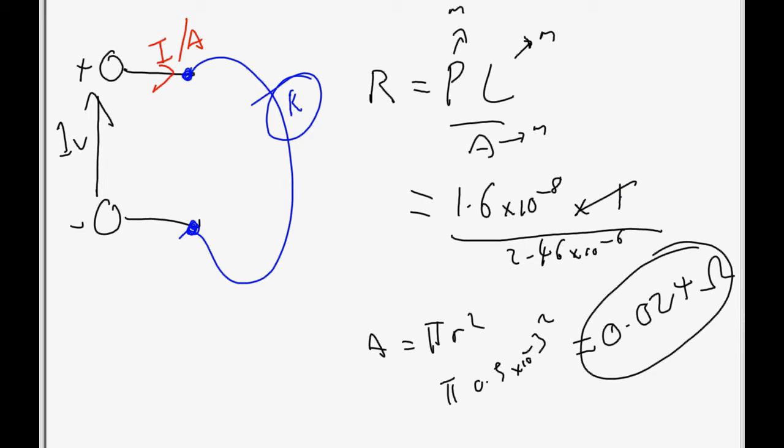So 1 meter of wire is a length. The diameter was 1 millimeter. The resistance worked out to be 0.024 ohms. Done. That's how you work out the resistance of a piece of wire. Its length, its area, which are the physical dimensions, and its resistivity you use.